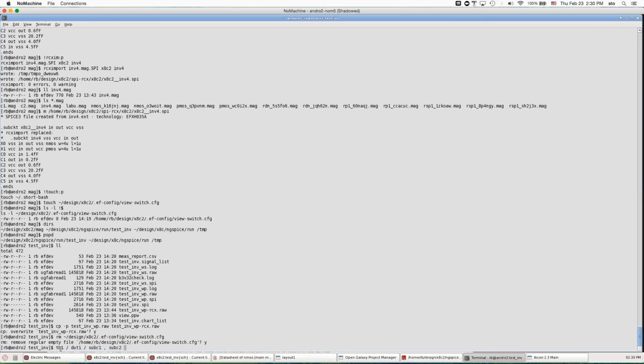So you have a hierarchical structure where, in the layout sense, these two will be placed side by side, forming the layout of DUT1. Now, I could do layout extraction individually on these, and run a simulation such that the test bench is a schematic, and the DUT1 is a schematic, and these two are getting it from an RCX view.